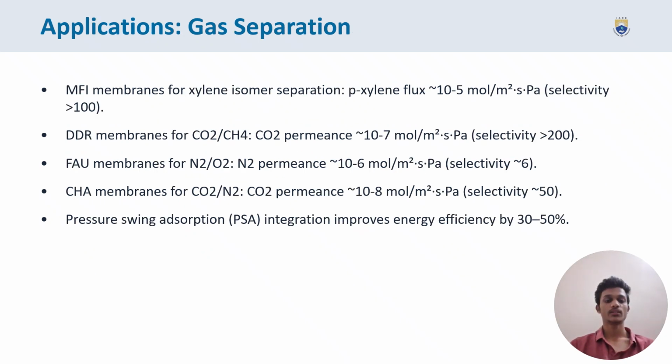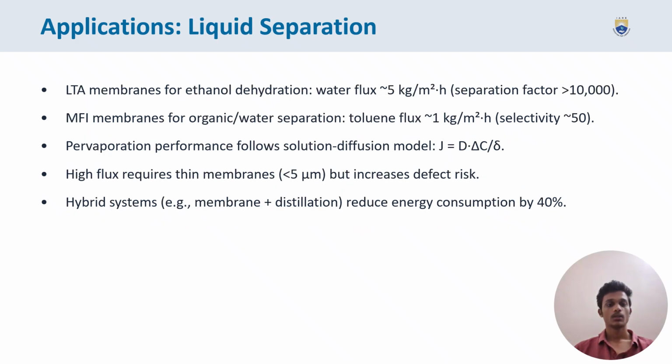Applications, gas separation. MFI membranes for xylene isomer separation. DDR membrane for CO2 permeance. FAU membrane for N2 permeance. CHA membrane for CO2 permeance. Applications, liquid separation. LTA membranes for ethanol dehydration. MFI membrane for organic to water separation.